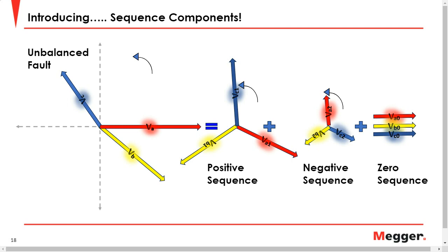Well, what I was saying is that I kind of gave that answer in the previous reply, and the reason is that since they have the same phase angle, the sum of the three equals 3 I0. When you have, let's say, a balanced system, the sum of the three is 0, so there's nothing going through the neutral. In an unbalanced system, whatever unbalance you have goes through the neutral. In the case of the zero sequence components, they all have the same phase angle, so the sum of the three equals 3 times one of them, and that goes through the neutral.